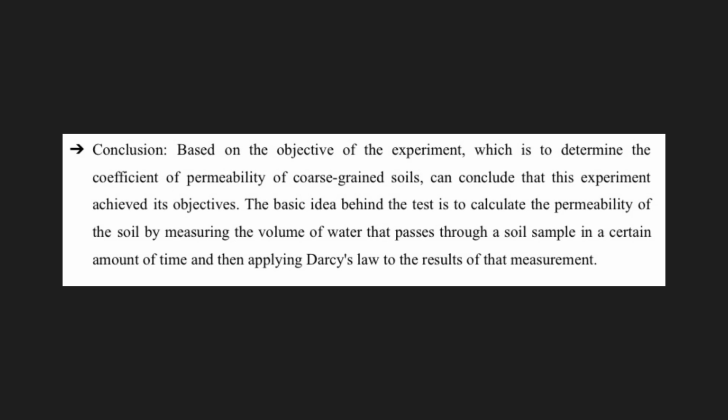The conclusion of this experiment, based on the objective of the experiment, which is to determine the coefficient of permeability of coarse-grained soils, we can conclude that this experiment achieved its objective. The basic idea behind the test is to calculate the permeability of the soil by measuring the volume of water that passes through a soil sample in a certain amount of time, and then applying Darcy's law to the result of the measurement.